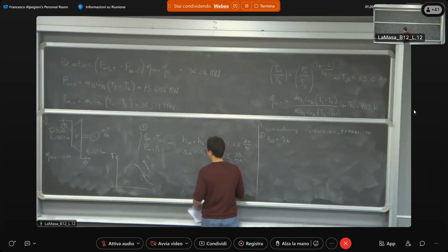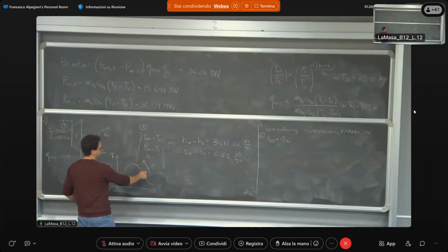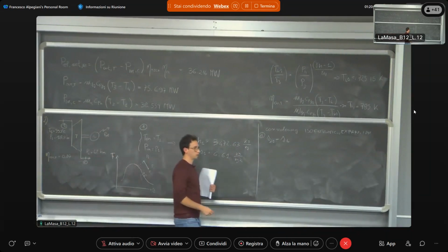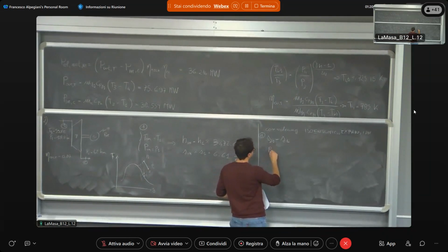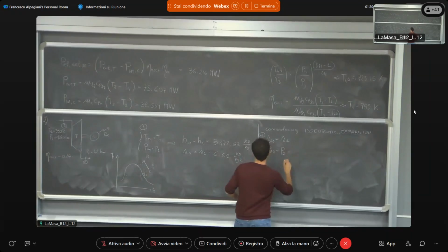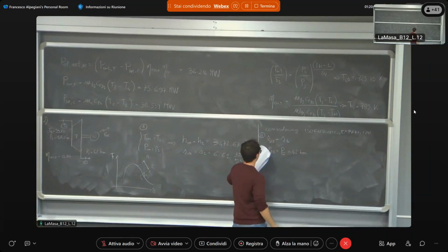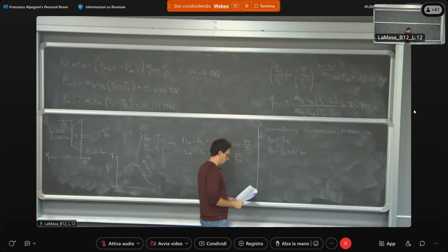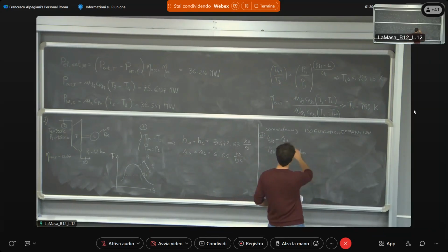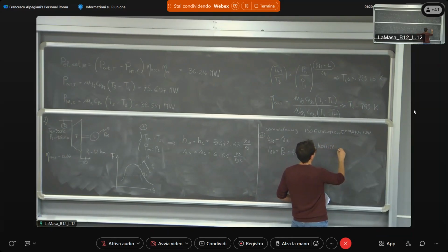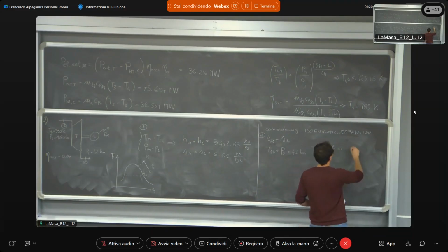Another thermodynamic property that we have in point 2S is the pressure, because the pressure is equal between point 2S and point 2. So we know the pressure of point 2S, which is equal to the pressure of point 2, and so equal to 42 bar. Once again, we have two properties, and entering the Mollier chart with these two quantities, we can derive the others.